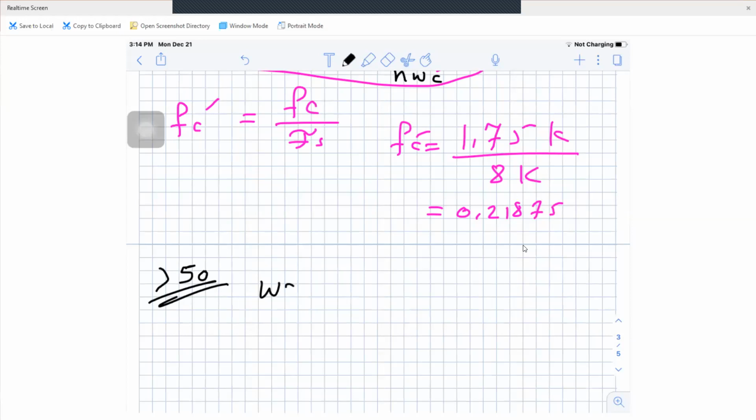Look, W of n equals 0.54 plus 0.46 cosine 2 pi n over N capital. Now, N capital is unknown for us. N capital represents what? The number of filter coefficients. It represents the number of filter coefficients.